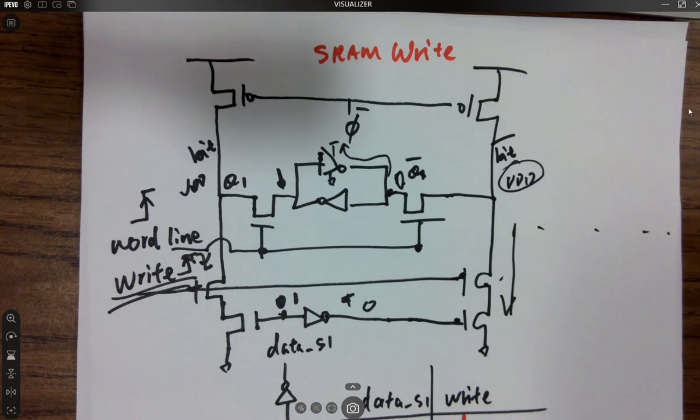That's critical, I can tell you, and that's why we switched from the Arduino Uno chip, which is only $1, $2, and it's a DIP microcontroller, can be easily soldered and tested on the PCB, and that was the Skyboard version 1. Just 2 weeks before the semester got started, when we were approaching lab number 8, we found out it's not going to work for lab number 8 because it doesn't have enough memory.